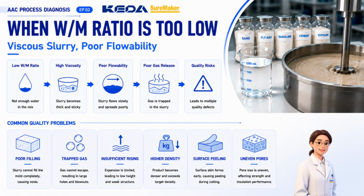If the water-to-material ratio is too low, the slurry spread value becomes lower than the design value. The discharge speed becomes slower, gas generation becomes slower, and the slurry expansion process may look relatively sluggish. Several problems may occur in this situation. The slurry viscosity becomes high.